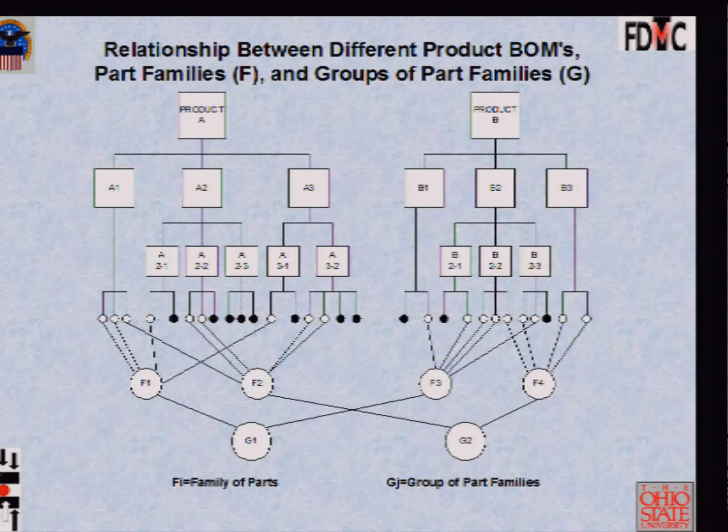If I may hazard a guess, all you would do is take all the components from the various products you make, and in the part numbers that you create, put a little string which identifies or associates each part number with the final product it goes into. And then run that entire group of routings into FAST. When you get the families of parts, you will know if a family of parts is unique to a product or whether a family of parts is actually built up of components which will go into many products.